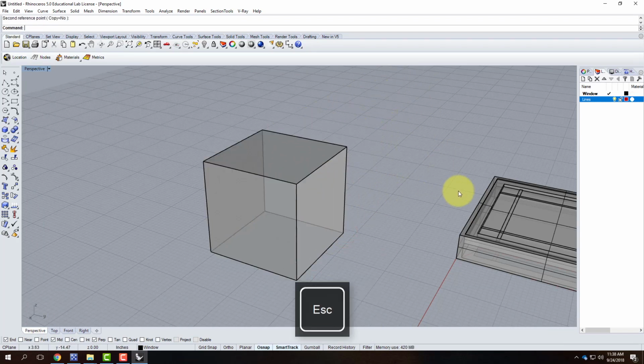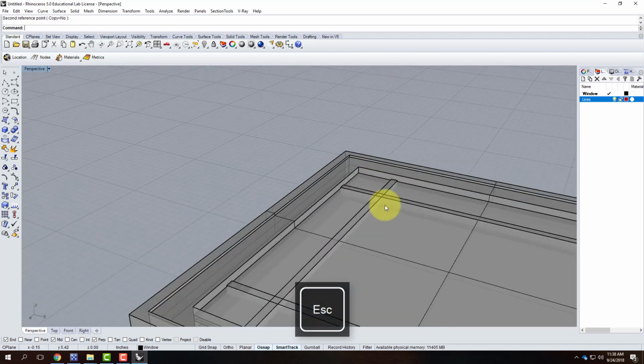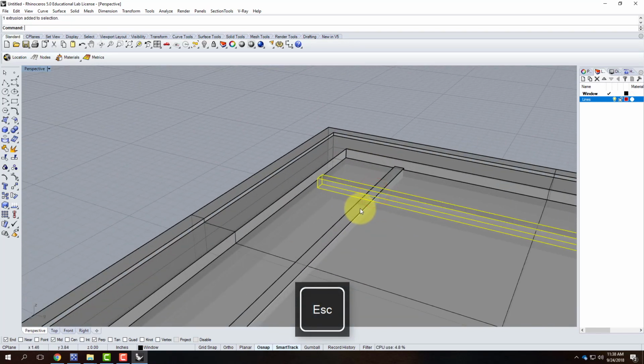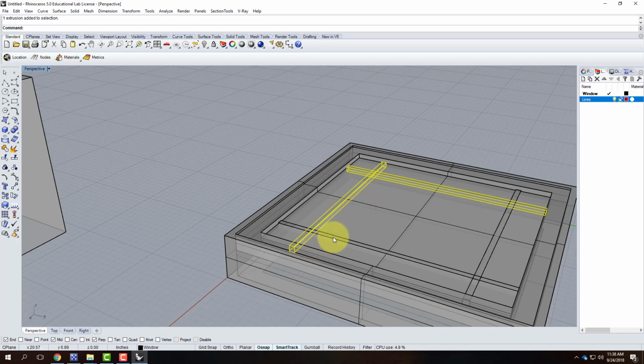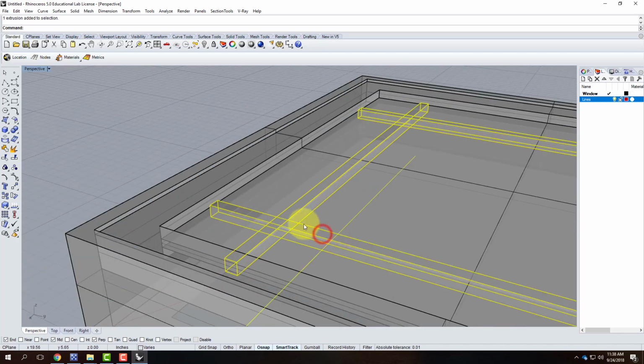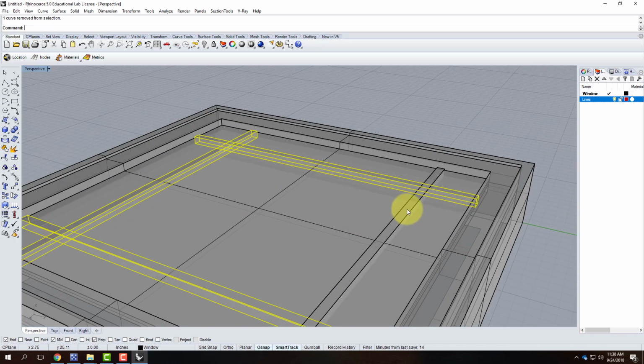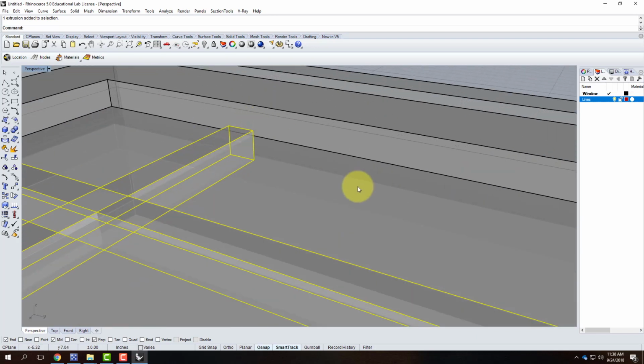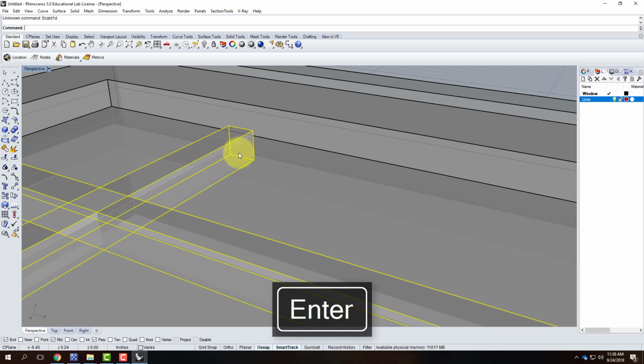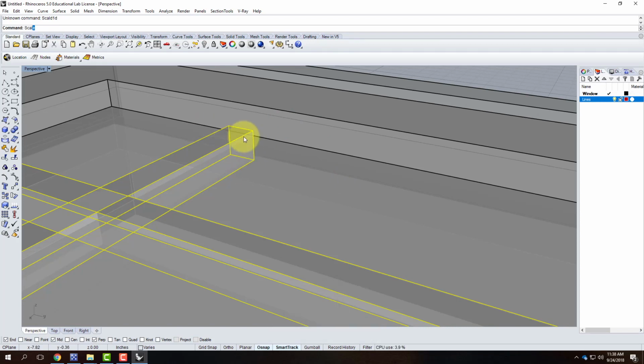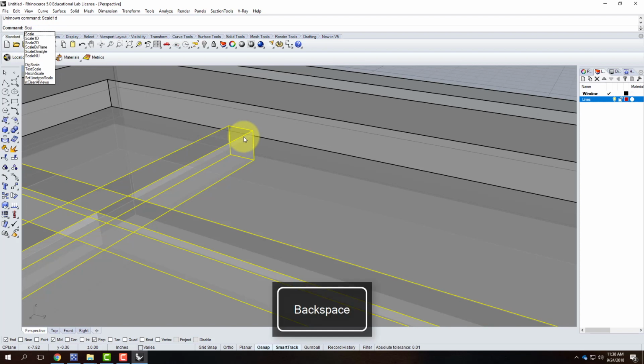So this can be really beneficial on something like these little mullions, because I wanted those to get thicker. So I'll take them all at once. I'm going to scale 1D, and I wanted that to be a total of 1 inch instead. Oops, scale 1D. Apparently I can't type today, sorry.